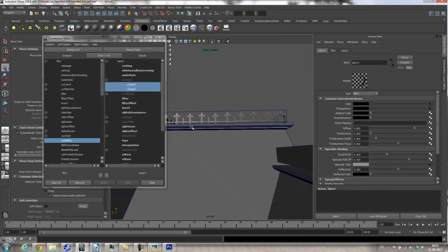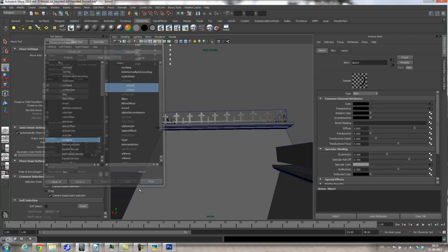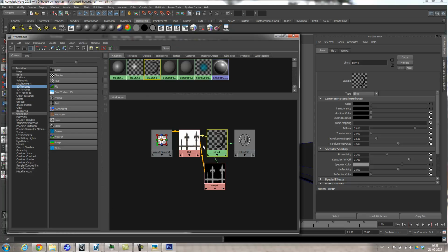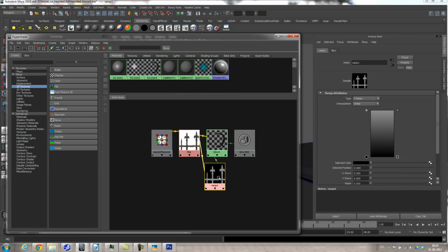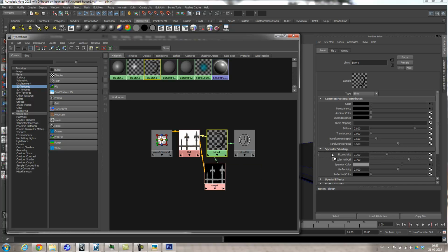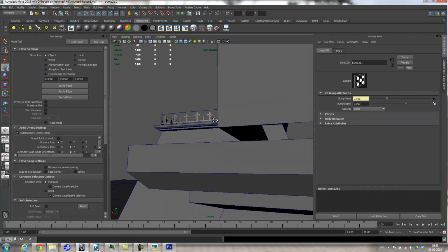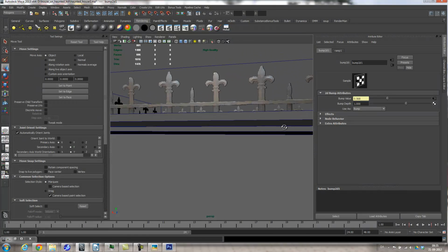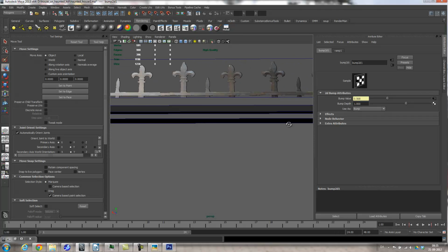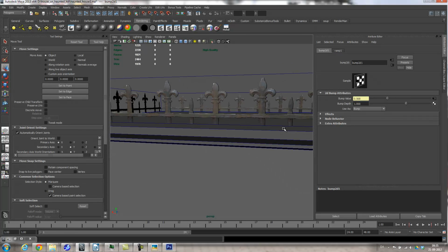And I can use the same method for my bump map. So if I use this, I can just middle mouse button drag that to the bump section, and you should get the impression that it has a little bit of structure, right?